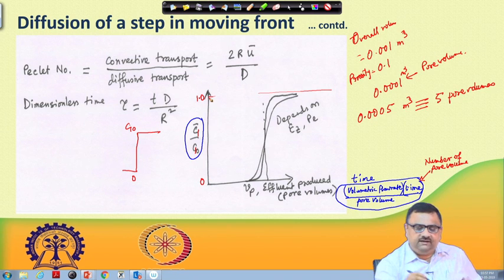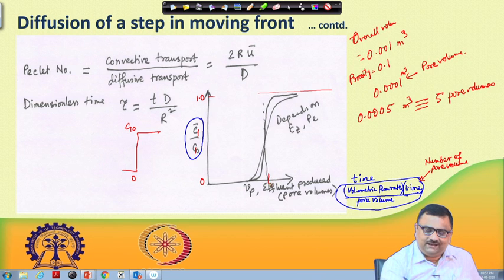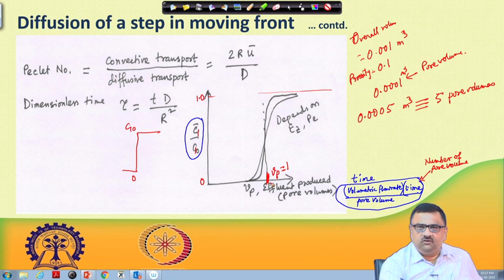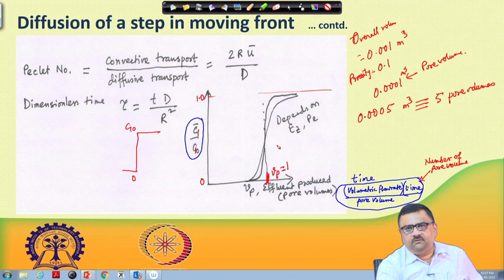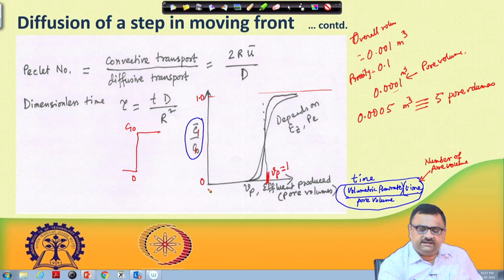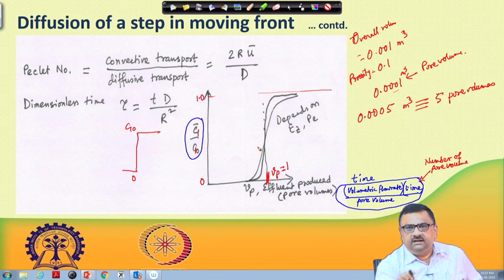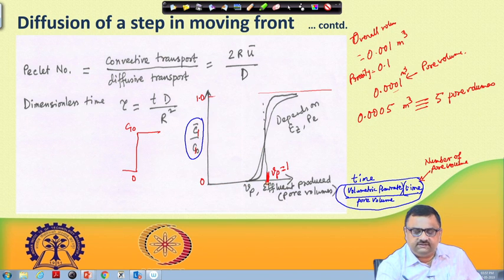Now, if we had given a step change, we expect that at V p equal to 1, that means 1 pore volume, equivalent to the residence time, which is 0.0001 meter cube given the overall volume and porosity, this is this point. If there is no smearing, just plug flow and no mixing, I would have expected it to be all 0 and suddenly boom, it is 1.0 and continuing.